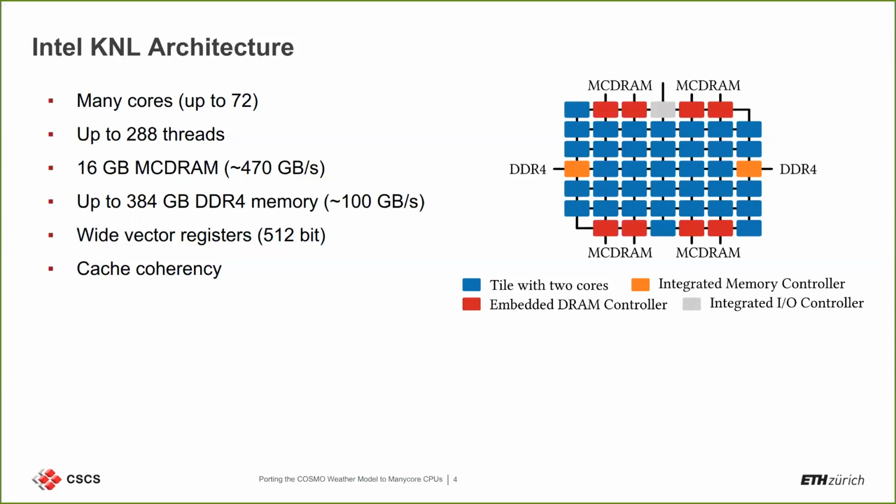This is actually the biggest difference compared to the previous architecture, the Intel KNC, where all communication was on a ring bus. So this was a great improvement, because cache coherency costs quite a lot with so many cores, and on the KNC the communication in this ring bus was often very slow.